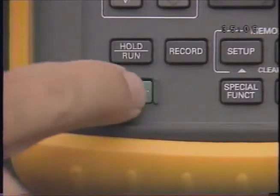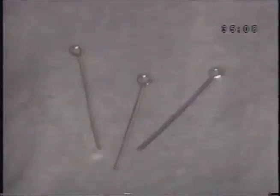In this exercise, you'll use Scopemeter's meter function to check a Ford map sensor's frequency signal. In addition, you'll see how Scopemeter's record and min-max features can capture signal glitches. Turn Scopemeter on and backprobe the map sensor's signal output wire with the backprobe pins included with Scopemeter.